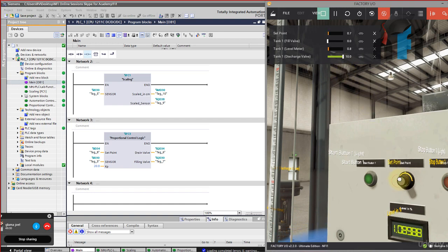We will see that. So let's say we need 18%. This valve is 100% open and quickly closing. Now you will notice that the level has been increased to 1.9. Although it will be compensated by drainage, there is an overshoot. Okay, so in proportional control, if you increase the gain more, you will get an overshoot.